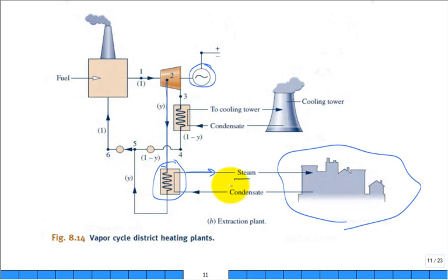They actually have 2 chiller plants down there now because of the number of buildings and square footage they serve. But this is very used in bigger cities up north where they have a significant winter. And it makes sense. On moderate days, they don't need a lot of heating for a lot of the buildings. Just very little goes this way, and you may just make electricity. Doesn't this make sense? Yeah, and engineers design it and run it.